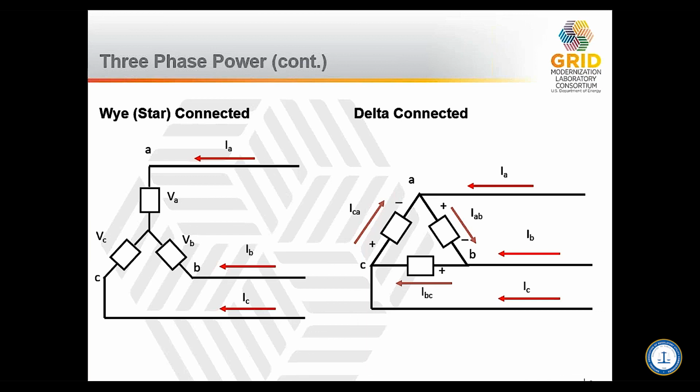So I'll talk about this a little bit more, but in general, at the bulk transmission system, kind of the super highways of the power system, we use these delta connected systems on the right, but when we go to houses and loads at the lower voltage levels, we tend to use a 4-wire system on the left. The left is showing 3 wires, but it's not showing the 4th wire as the ground. The point being is that there's complexity in how you connect these different systems.